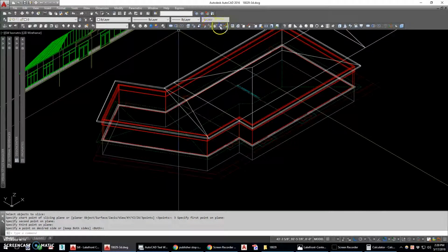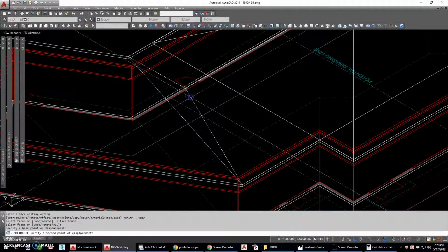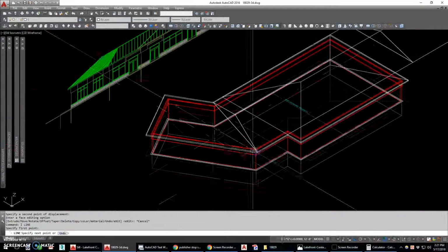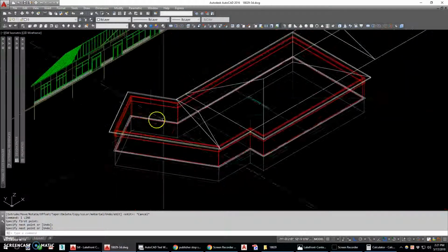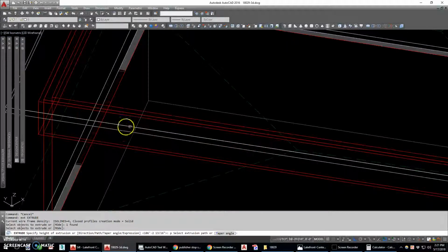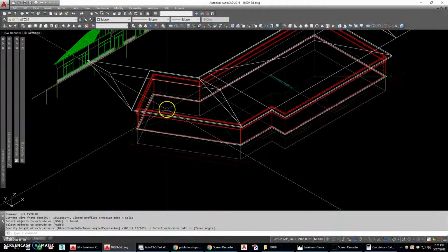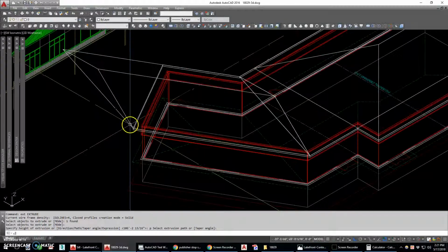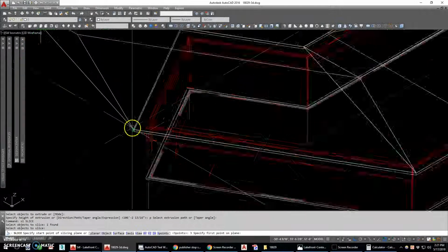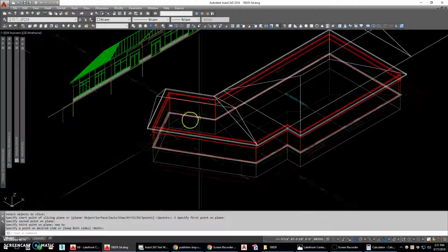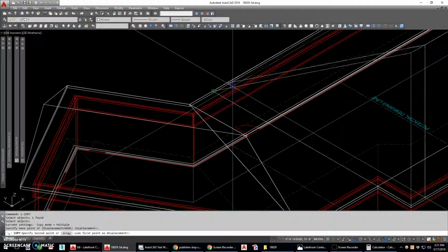Now hopefully I can take this face, copy it. Now if I draw a line for it to use to extrude, I can say extrude along a path, pick my last thing. Now again, it's wonky, but we can go ahead and get what we want just by slicing it, 3 points, keep this side, and then I've got to get an angle on that roof.